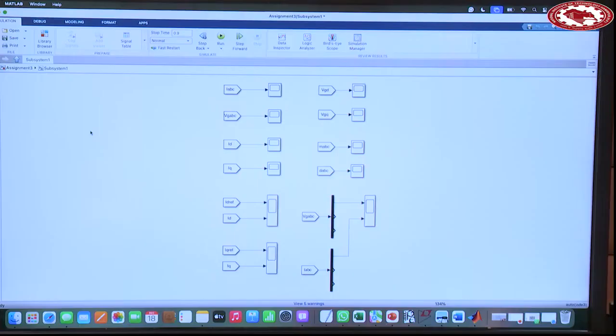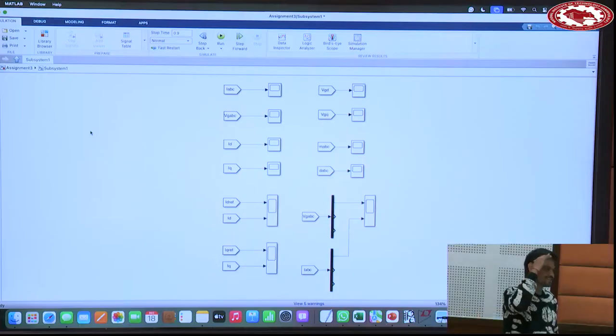So the DC link voltage increased, reached the threshold limit, and the circuit breaker tripped. That's why this switching was happening. So I should tell you that more DC link is required if you are operating the same structure as a STATCOM rather than simply as an inverter.